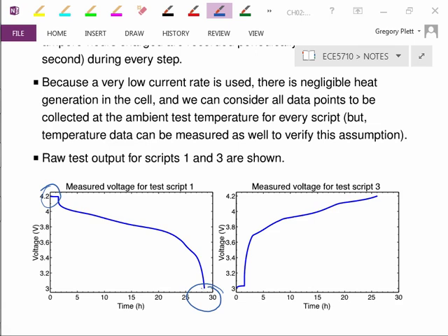So the nominal capacity of this cell was used when we designed the test, but it turned out the actual capacity of this cell was below that because this was an older cell that had already been used in some application before I did this testing. And so instead of the C over 30 I thought I was getting, I really got about a C over 27-ish result. And that's okay. The C over 30 is not magic.